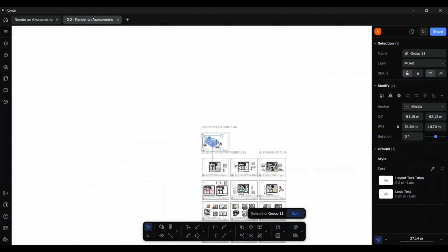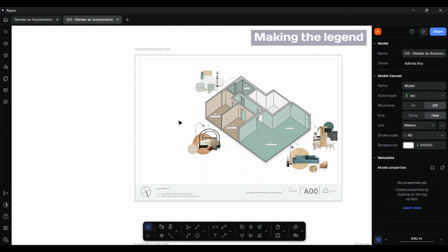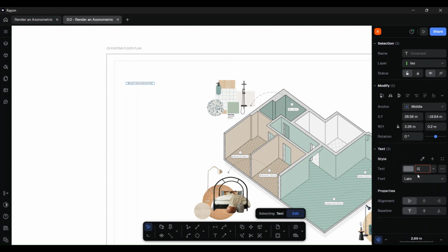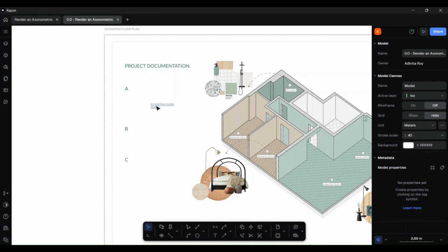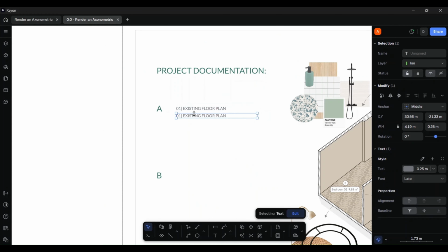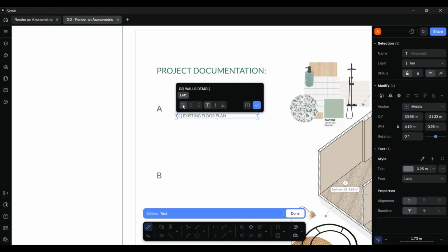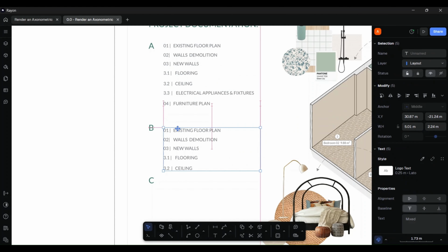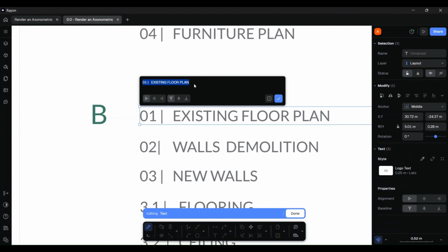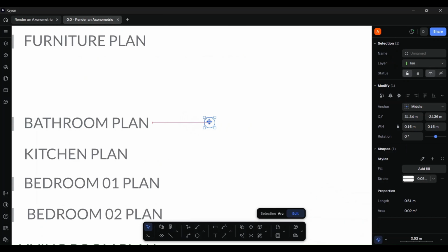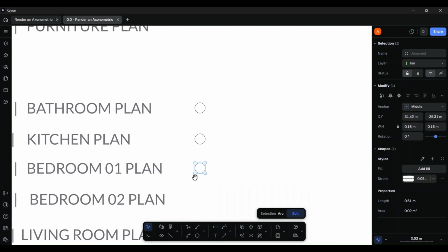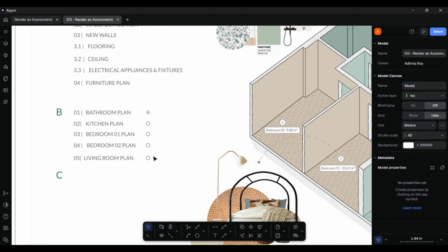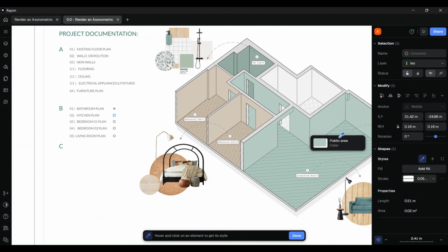Once you place your diagram on the sheet, do not forget to add a legend for clarity and readability. Use the text tool to write the required information and keep an eye on the Style tab to the right to change font styles, size, and color, or save your own labeling style. Use the Pick Style tool while filling in the colors for the legend. This not only makes the task more efficient, it ensures consistency in the colors used.